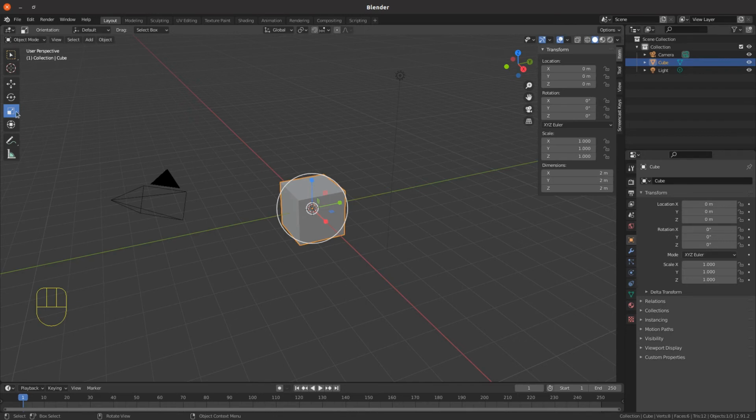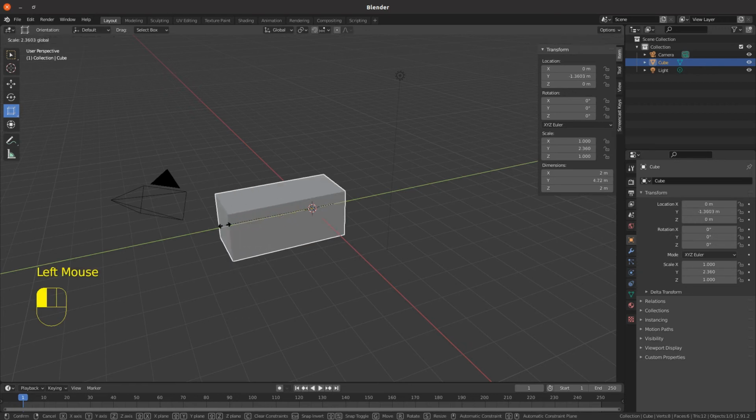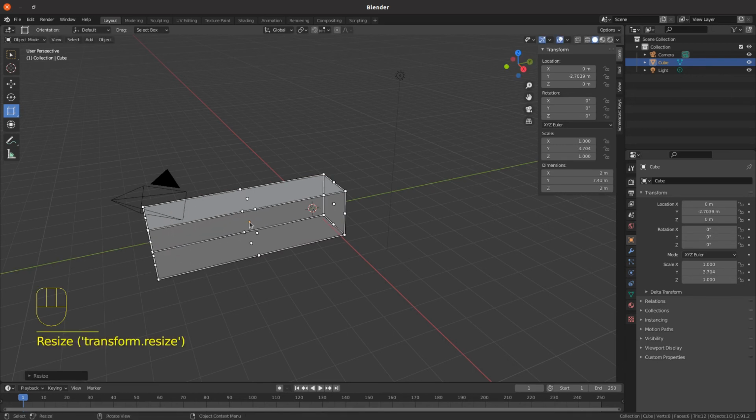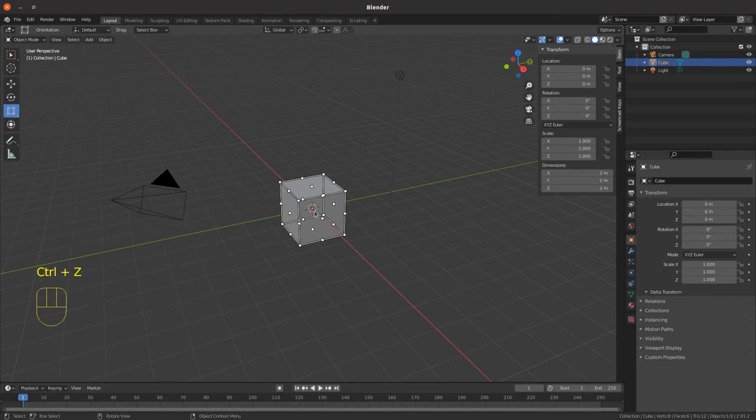If you look at the toolbox, there's a little triangle in the corner, which means if you hold your mouse with the left button down over that icon, it gives you a second option, which is the scale cage. This gives you options where you can scale and just drag out on one side, so you're actually just moving one side of it. You'll see as it moves, you're actually moving the origin as well as scaling along. So it's no longer scaling central to the original position. Control Z that. You can see the origin's gone back now to its normal location.